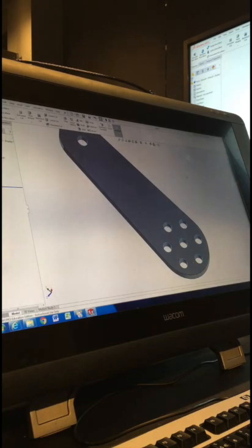Why can't I dimension my circles? Okay, you can, but it's saying no, not while you have 3 things selected at once. Oh, okay. So grab your dimension tool, click the circle, and then drop it. There you go. Did you manage to make them all equal? Yeah. So you want to make all of these the same dimension so that they all have a relation that's equal? I just did the one on top.